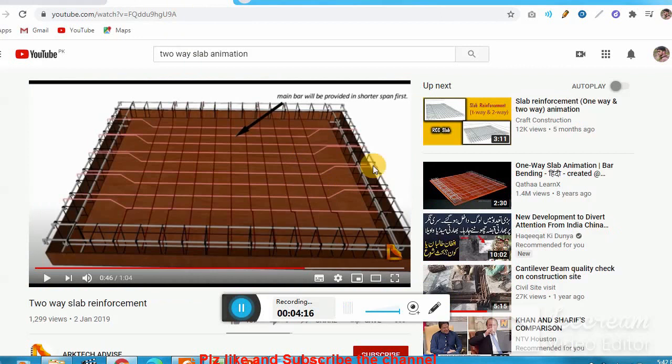Let me show you another video. You see here one bar is straight, the other bar is bent up. But the most important thing which I already explained is that one side of the bar is bent up, the other side is straight. Now for the next adjacent bar, the opposite side edge of that bar is bent up while the other end is straight. This is called alternate bent up bars.